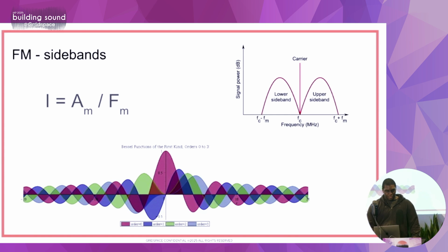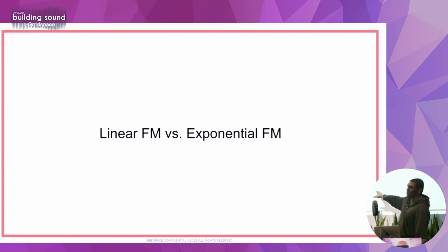So I've been calling the input to an operator a pitch input specifically because of the realities of how pitch is controlled, in that the DX7 and most FM synths operate using something called linear FM, where the frequency input is modulated in hertz, whereas you can also modulate something using semitones pitch, because that's how in modular synths a pitch is expressed, using voltage that's mapped onto semitones.